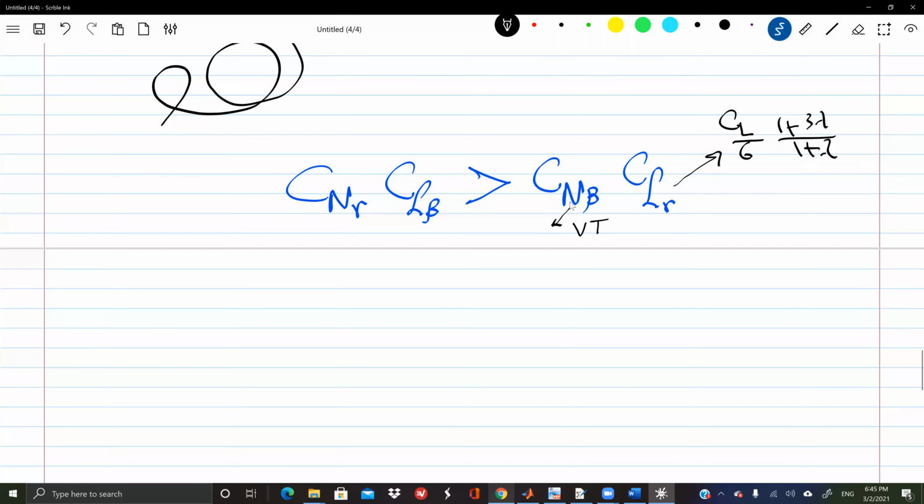So I cannot, at my own discretion, decrease Cn beta. Although I can if I want, but I will not be able to do so because, you got the idea, I will make the Dutch roll mode, which is a very important mode, worse. Okay, so that's fine, I cannot decrease the right-hand side. So let's go and try to increase the left-hand side to satisfy the inequality. What about CL beta? Can we increase CL beta? Well, yeah, you have several sources. You have gamma, you have sweep, you have many sources to increase CL beta. Any concerns, folks, about increasing CL beta?